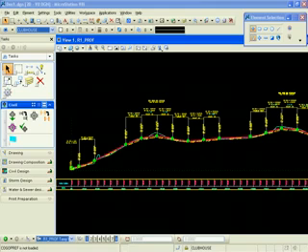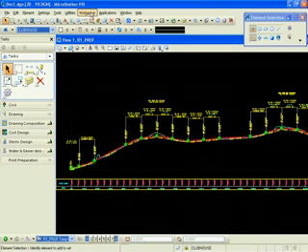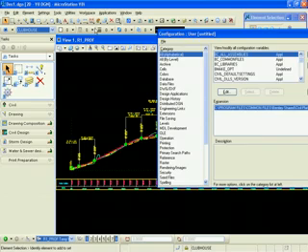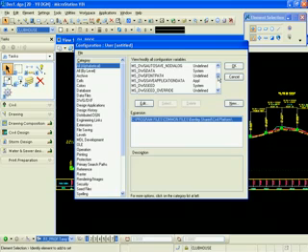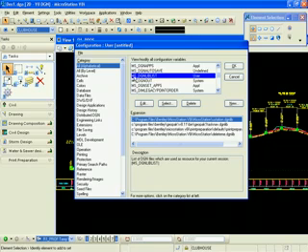Okay, we want to look at customizing a v8i task menu using our civil tools. In the workspace configuration, we have a variable to point to our DGN libraries that contain our customizations. Under MS DGN we can navigate to and select various task navigation customizations DGN libraries, and we can store as many of these as we like.